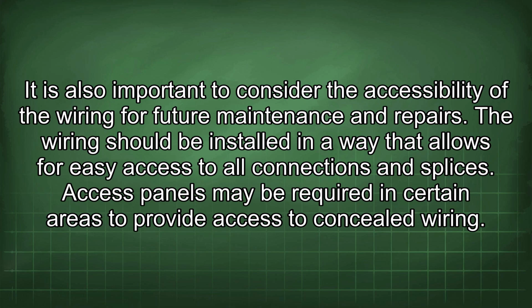It is also important to consider the accessibility of the wiring for future maintenance and repairs. The wiring should be installed in a way that allows for easy access to all connections and splices. Access panels may be required in certain areas to provide access to concealed wiring.